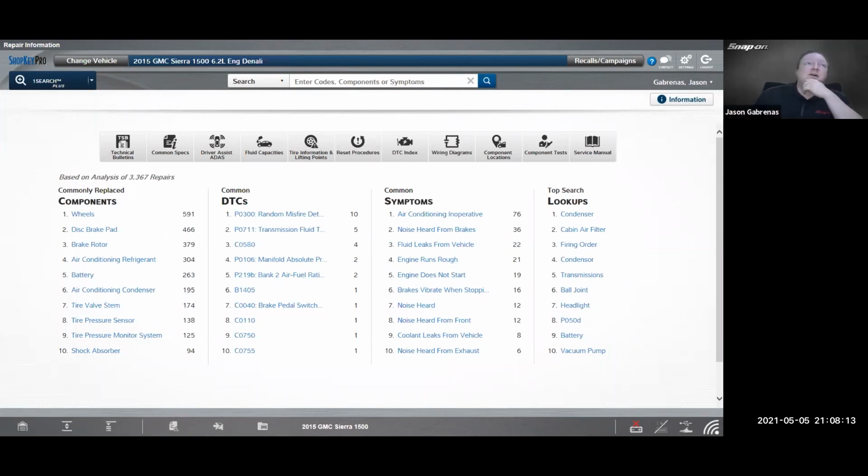Let's see, Tim Richardson asked, do you test with key on engine off or key on engine running? Could be either way. Those patterns that I captured, any of the patterns are just key on engine off. If you don't have any data transmitting, you might want to turn the engine on, then you might get a little bit more data going on there.